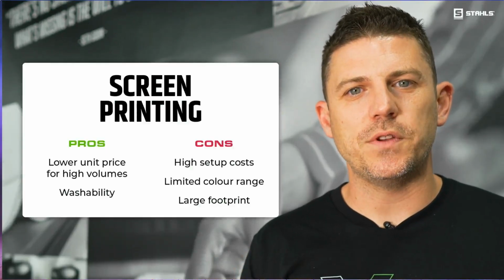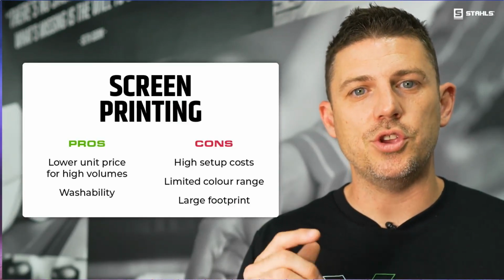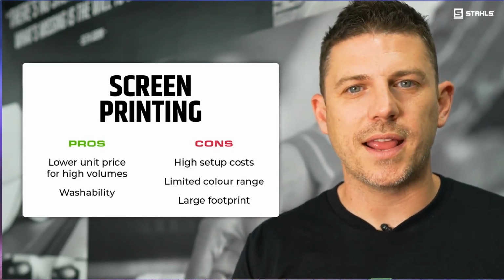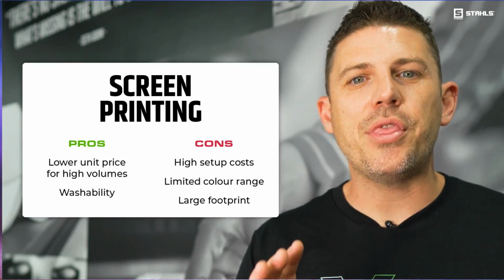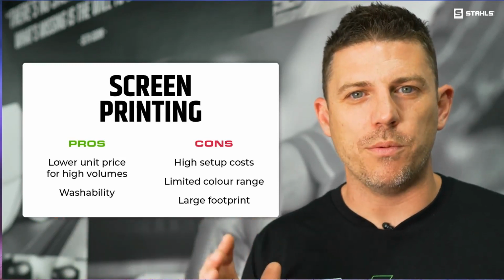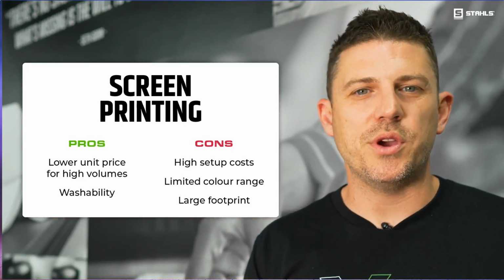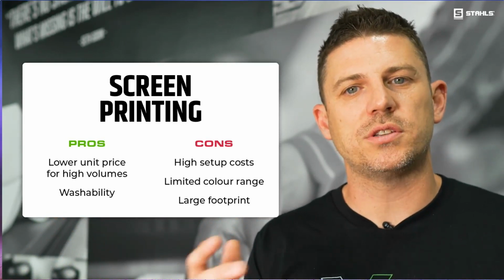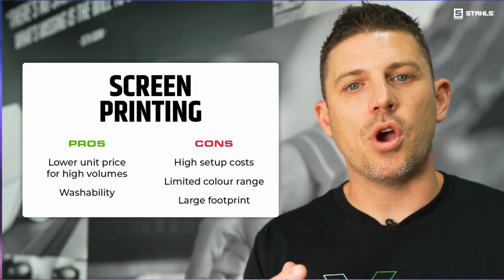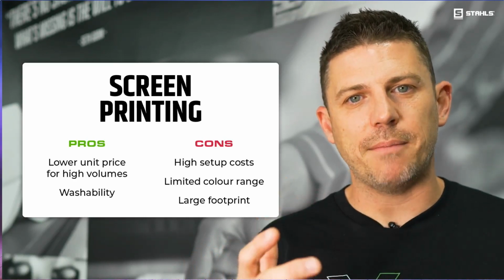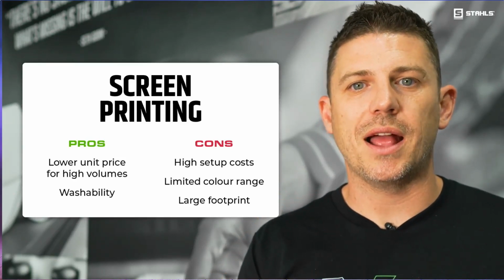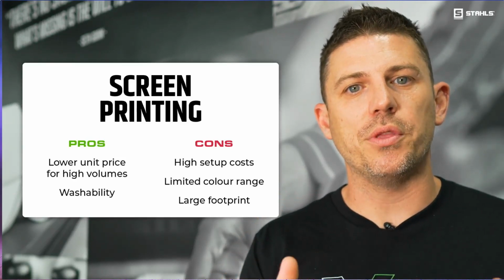We've got screen printing. Screen printing is the choice for doing small color designs or low color designs, so one color, two color designs, and the higher quantity volume orders, okay? We don't want to be doing ones and twos and threes, fives or 10 units of screen print. It's just not cost effective because of the setup. So cons, you've got a setup cost with screen printing, okay? And con, it is one to two colors only, okay? So it is limiting on the design.